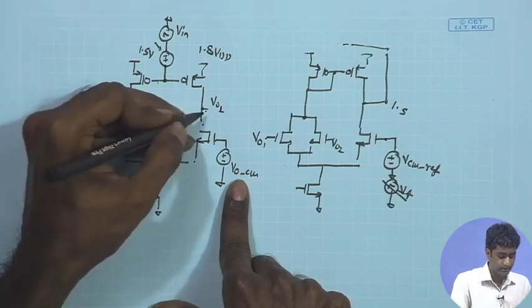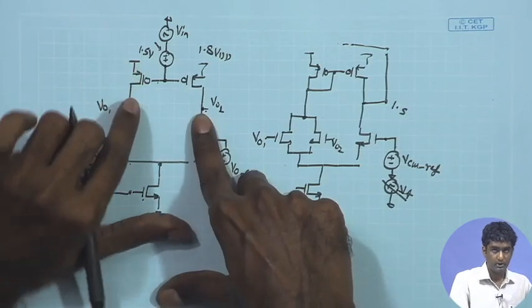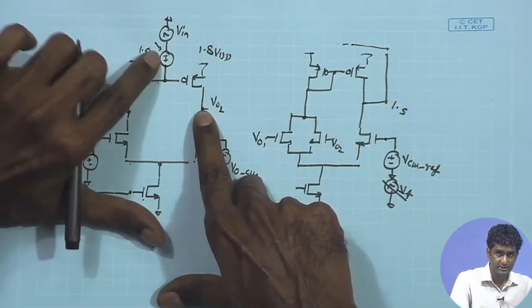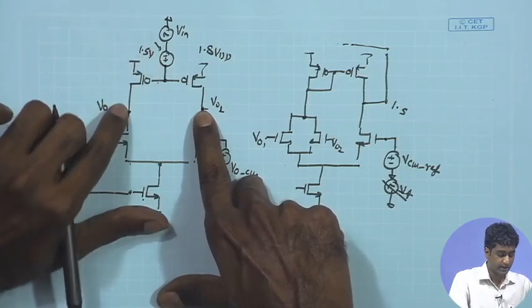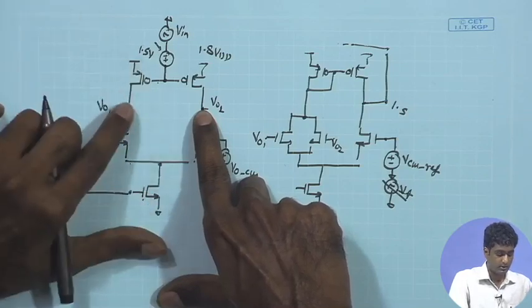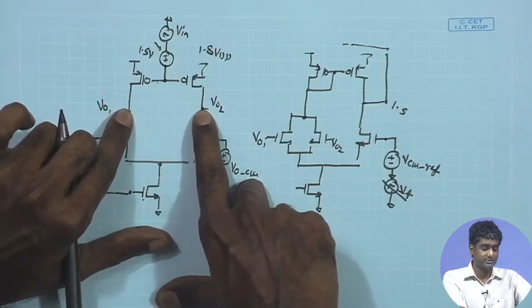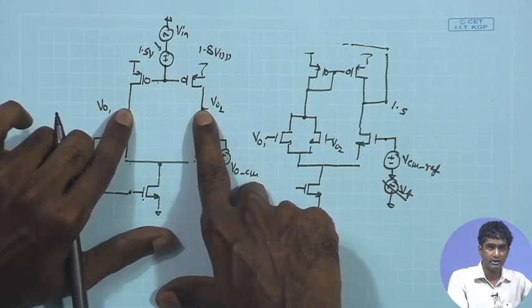Now, if we therefore want to look at the signal over here, a small change in the DC level, even 1 millivolt of change, can produce a large shift in the DC potential over here. Remember, we are designing this circuit for an overall gain of greater than 10 to the power of 4.